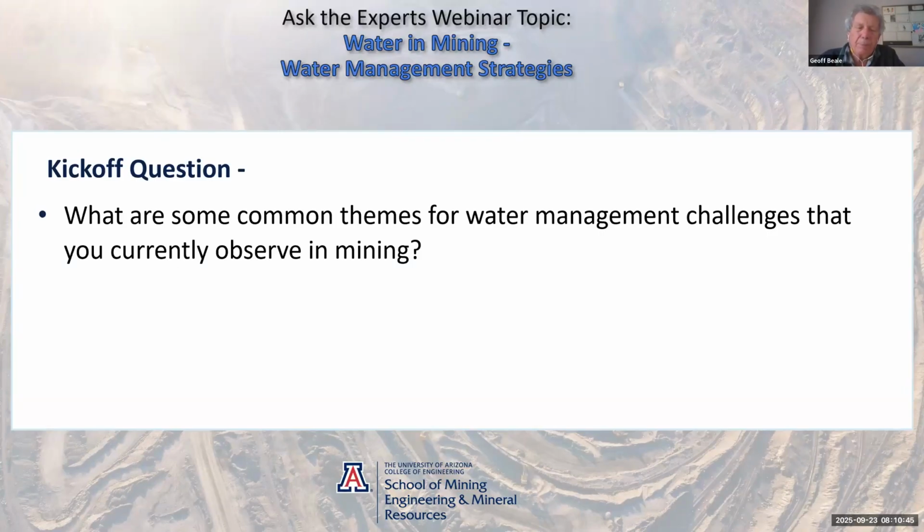I think we have a lot of challenge at the moment with particularly older mines that are mining slopes at a somewhat lower factor of safety. They design slopes to a factor of safety of 1.3 or 1.4, but find they can't make the economics work at those factors of safety, so they've got to switch more to an observational mining approach with lower factors of safety, and that requires very, very good depressurization usually to make sure that they don't start to create instability because of water.